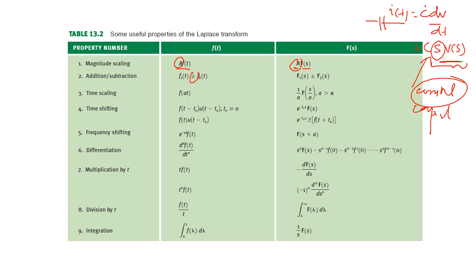No change in the value of the constant. If we are having a plus here, we will get a plus here as well. A of t, since it is multiplying with time, a multiplier with time is a division in frequency. So in the frequency domain, it will be a dividing thing here as well. Time shifting: if we shift something in time, its frequency will not change, which is obvious, since frequency depends upon the speeding up or reducing of vibration, not the delay or advancement of the signal.